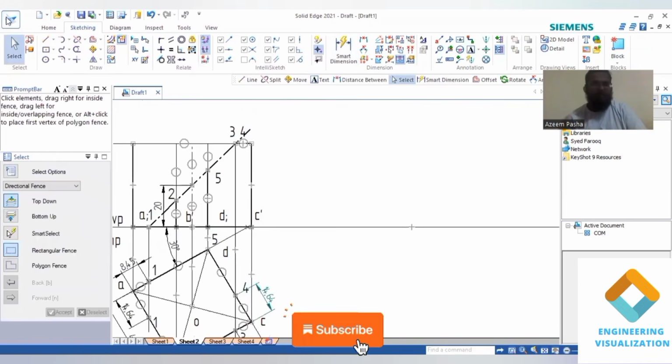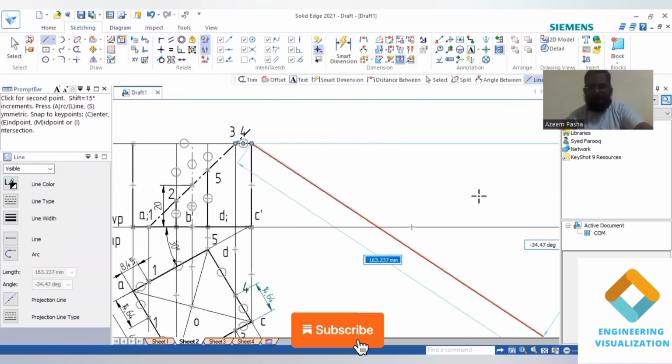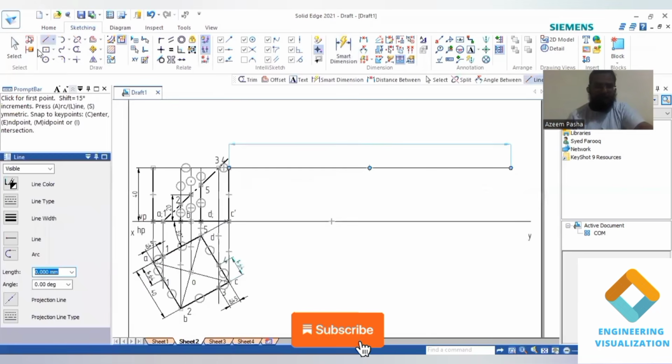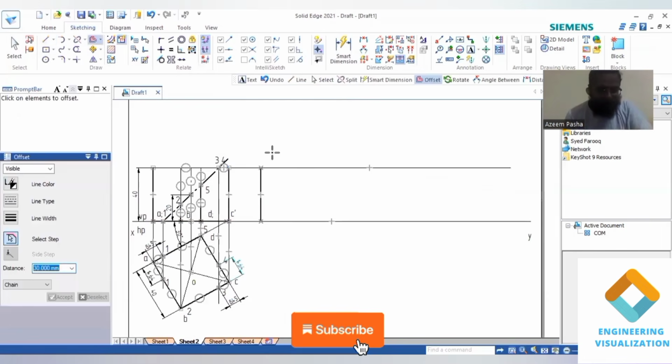Now we draw the development of this. So we are drawing a parallel thin line here, a straight line. We'll draw a vertical line here. Now using the offset command, I'll be taking 4 faces here at a distance of 40.